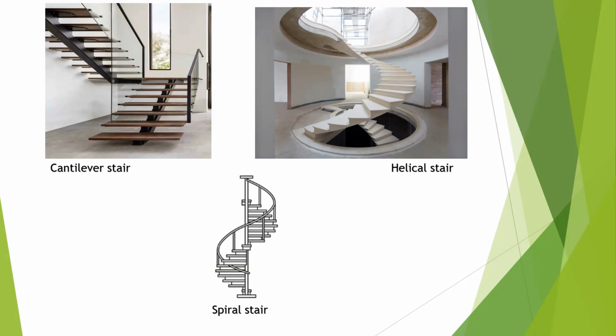You should be sure that your designs are appropriately done before you recommend that kind of stair. You must do your design very well for that kind of stair because there is no support at the landing, and you can imagine the forces that the stair is going to be subjected to.